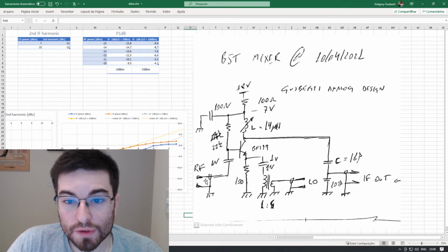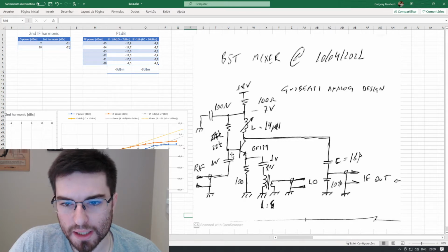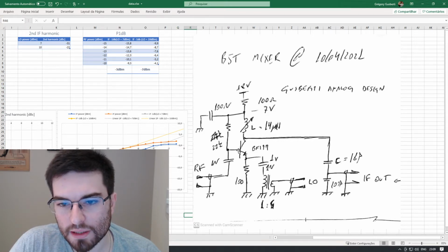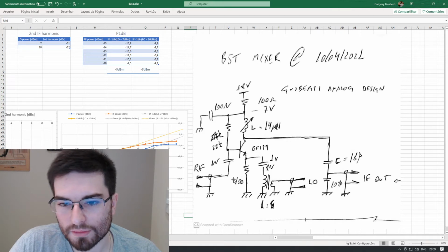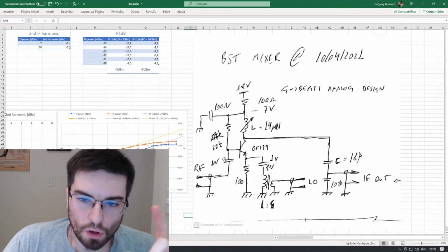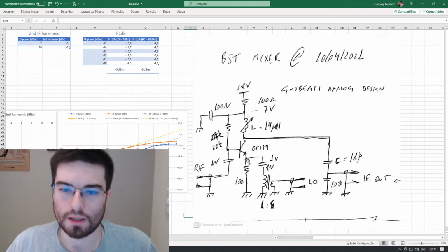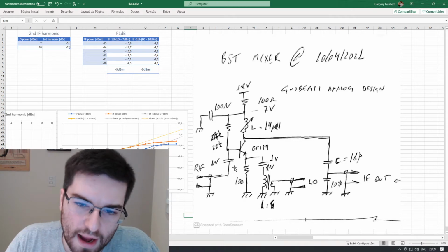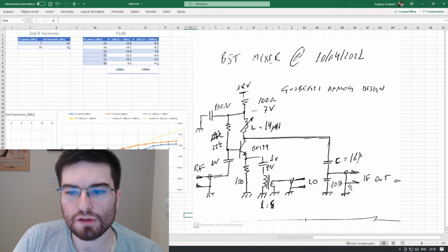And for the radio frequency power in the base, we have a common emitter stage. It's very easy to see here that we are amplifying the RF signal with a common emitter stage, because we will consider that the LO is grounded for the RF power. So we have the transistor operating in two different ways for the LO and the RF. But what is important is we are injecting the difference between the LO and RF in the base emitter junction.